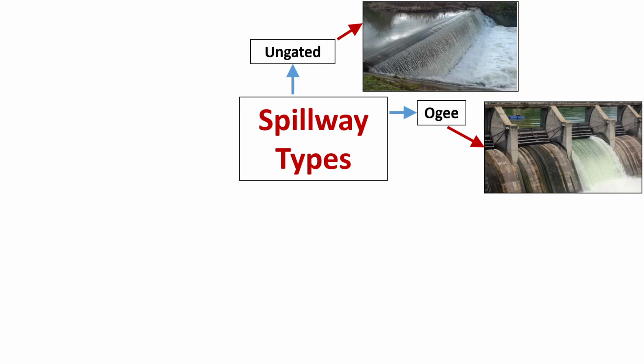Since this spillway is located almost near the dam top, and we all know discharge is directly proportional to head, since head is less, the discharge is less and it requires more space to accommodate the gates. In some places, where design discharge or flood is more and space is limited, these spillways cannot pass more flood. Either flood routing, that is, flood is absorbed in the reservoir, or a better spillway has to be adopted.